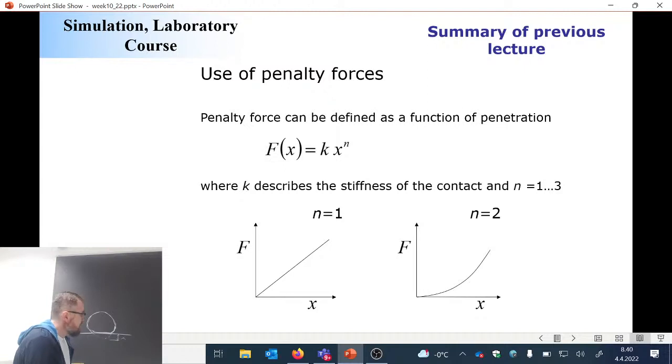To make it computationally more stable, and also a little bit more physics-based, it is sometimes a good idea to have damping on it. You just need to be super careful because certain damping models damp the motion when the ball is moving in this direction, but they also damp the motion when the ball is moving in this direction. And that's not physically possible.